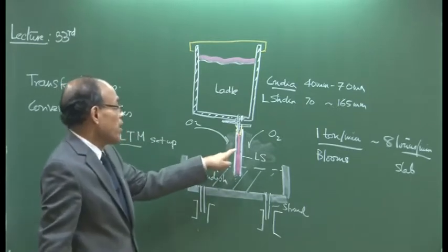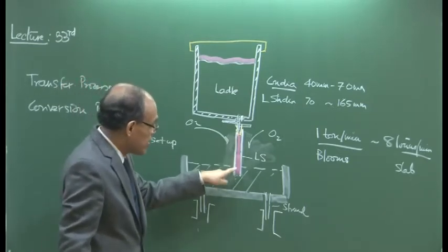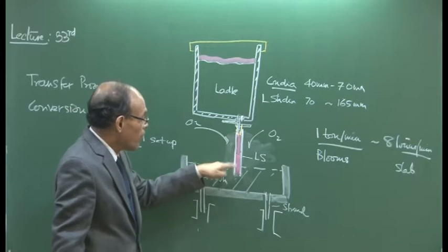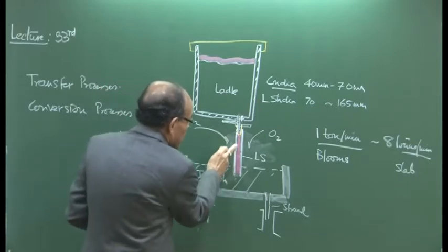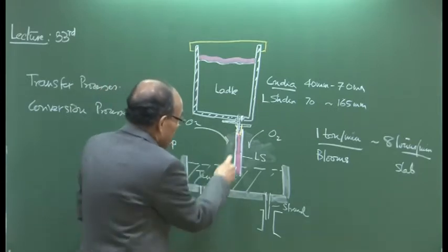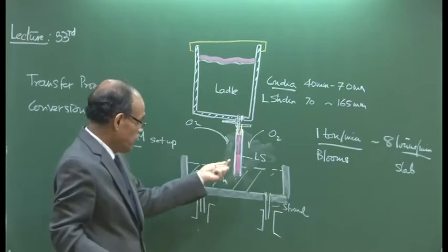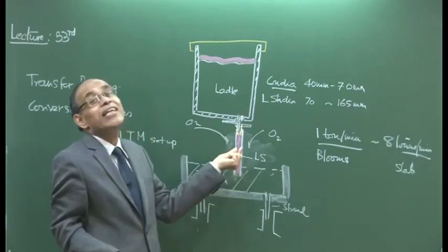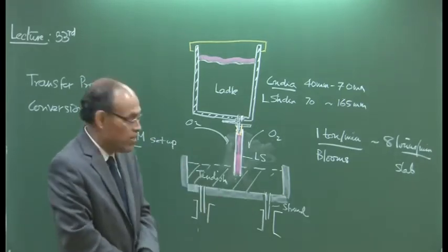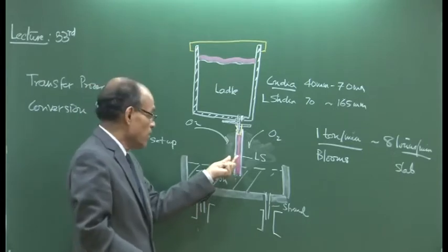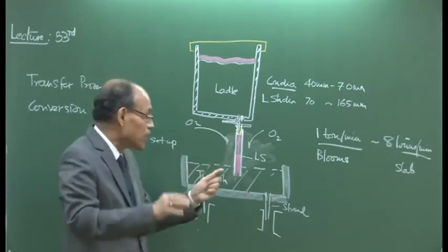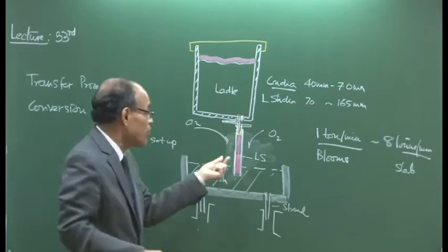This is a severe air aspiration rate, where molten metal has entrained quite a bit of gas, and this empty space is the gas between the white line and the red line. This is a jet which is severely constrained, and this is a free jet. It is not in touch with the wall, but it is a severely constrained free jet.